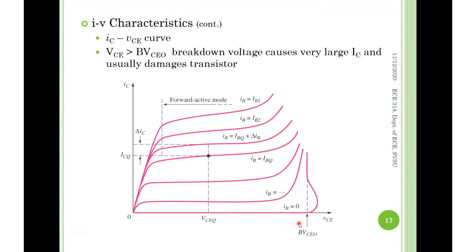It's short. Basically shorted, right? We call it breakdown, that's okay. But basically what you're seeing is the current is boosted up without taking much increased voltage. This is how we interpret this phenomenon: the current goes up quickly without much difference in the voltage.